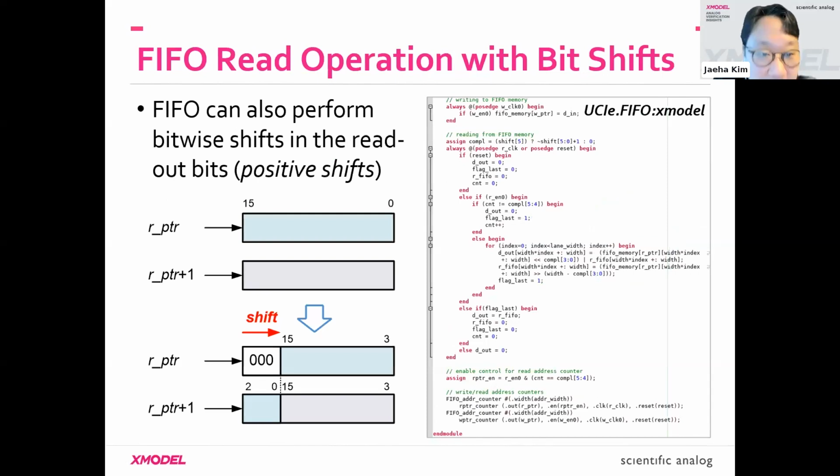Now, we need an additional capability on top of this basic functionality. That is, we need to be able to shift the phase. So even when the reader says, give me data, you pretend, oh, I'll give you a 0 first, and then start giving you the real data after some number of bits, which is indicated by the shift code. That creates the effect of shifting the data and causing additional delay in units of UI.